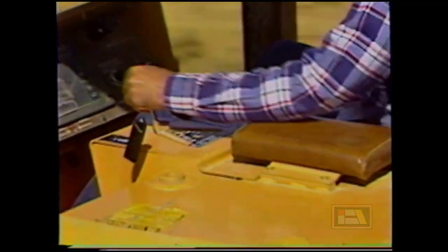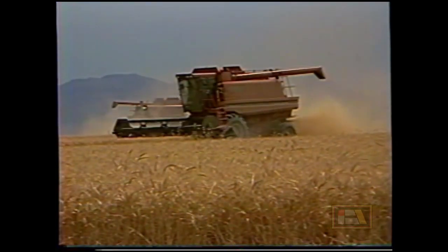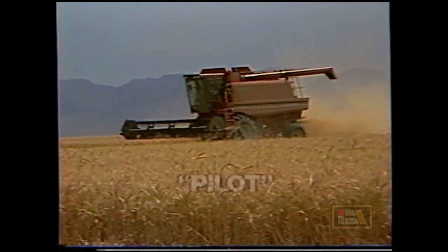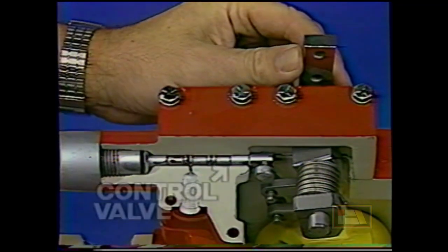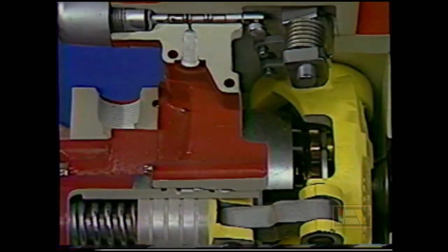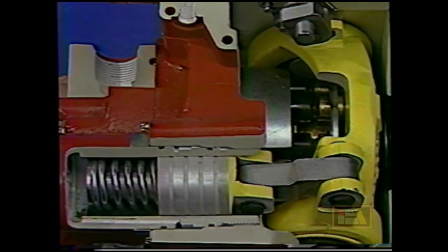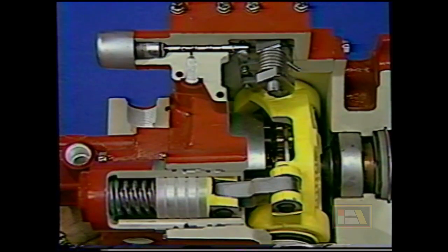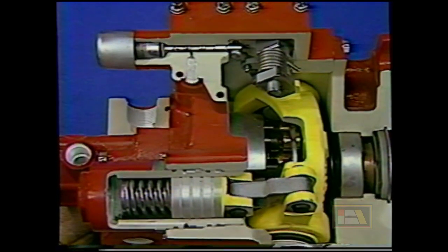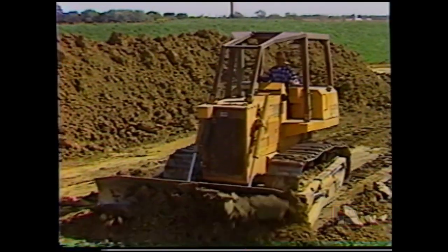Anytime you use a hydraulic system to gain control of or operate another hydraulic system, that is referred to as a pilot system. Usually, the oil provided by the charge pump is regulated and used as the oil source by the pilot control system. A hand or foot actuated pilot control valve then directs the oil to the servo piston, which controls the swash plate angle. With a change in position of the hand lever, the operator moves the control spool so that pilot pressure oil is applied to one end of the servo piston, thus stroking the pump and causing the unit to move.